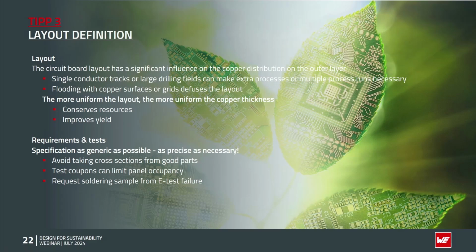We talked about test coupons, limit their use as much as possible, and you can request a soldering sample from an electrical test failure to set up your soldering process with a faulty board, so that you don't have to use a good one.